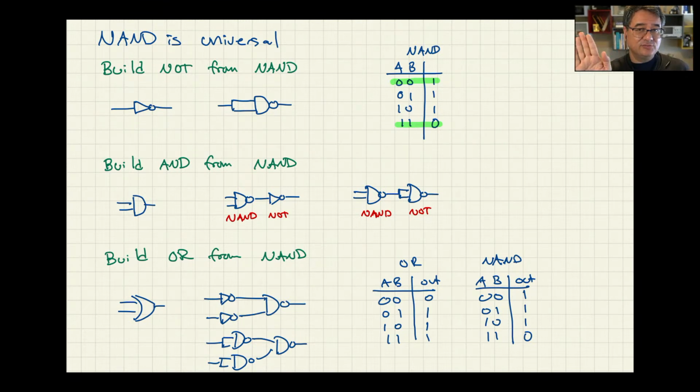Whereas the NAND SSDs were better for consumers, right? Cheaper and a little bit slower, and of course they don't get as much usage as a server one does. These days, the technology for the NAND SSDs has caught up to the point where they're fast. They don't consume nearly as much power. They're much more reliable. And so NOR SSDs have pretty much fallen by the wayside. The NAND SSDs are so good now that it's basically what you buy. So they're cheap to manufacture, and they're fast, and they consume less power. It's just because technology has moved forward. So yes, there is a tie-in with flash drives and SSDs.